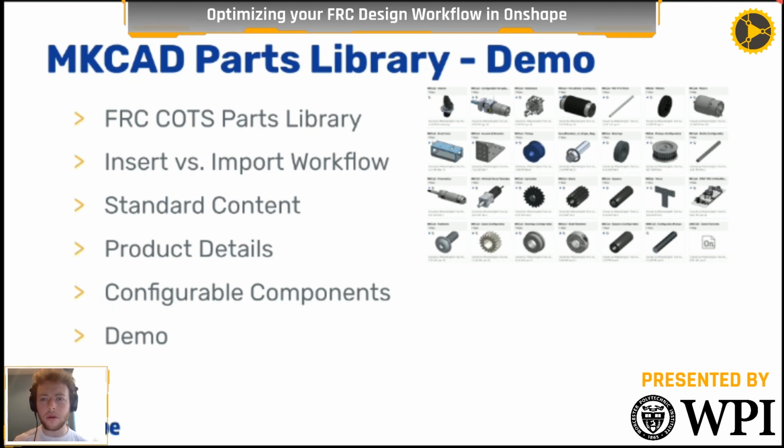I would say that they're fairly similar. My understanding is that even if you had configurable components in another platform, you would have to go back into the part file and change them. Right. This workflow is specifically designed within Onshape such that in the assembly or in the part, of course, but in the assembly, because you don't have access to these specific part studios, they're like deep in Onshape land somewhere, you can change them within the assembly, and you're only changing the reference to the original part studio.